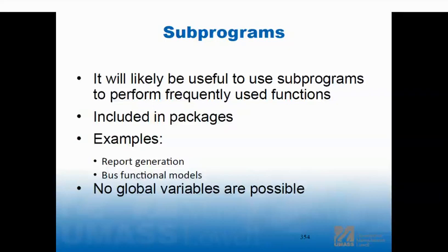So let's say you have to initialize the chip. And that's obviously the reset bus functional model, but you might have to write a bunch of registers. You'd make that its own routine. I'll call it a macro for now. And now a lot of the test cases would run that initialization routine. So all of those next level up would be in its own package. And then test cases are test cases, right? Those you just run as test 1, test 2, test 3. But just see how that structure is going.